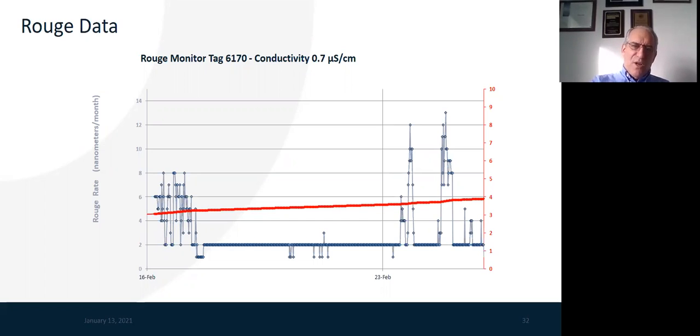to the heat exchanger. When the water goes down to 75 degrees C, the heat exchanger comes on, and there's a subsequent increase in rouge development. When the temperature goes down, you'll see that there's a decrease in the amount of rouge development. But because this oscillates up and down, you see that it actually stabilizes over time. It's running very, very normal.